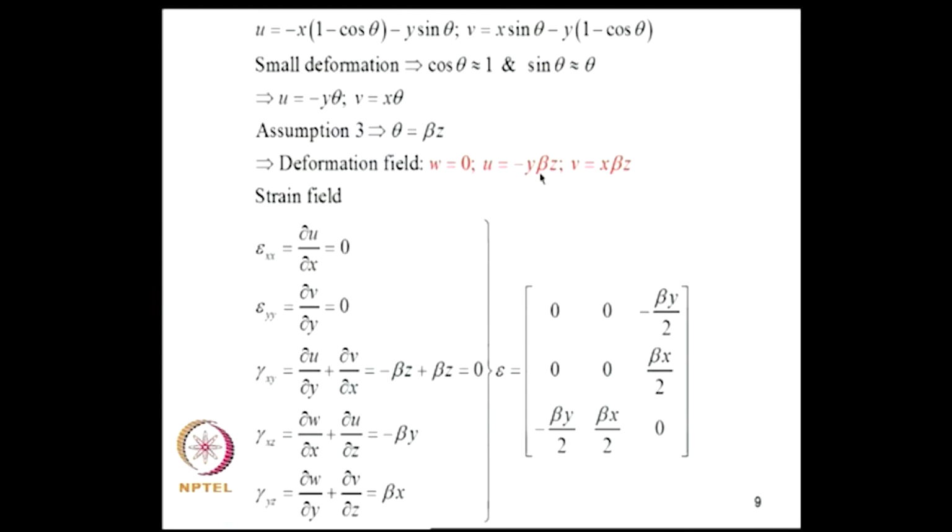Now, the task on hand is to see whether this satisfies the equations of elasticity. The equations of elasticity are basically the strain displacement equations, stress strain relations and equilibrium equations, and once we verify that this satisfies those equations, then we have to satisfy boundary conditions at z equal to 0 and z equal to L, and along the lateral surface r equal to capital R for all values of theta. So, let us run through that.